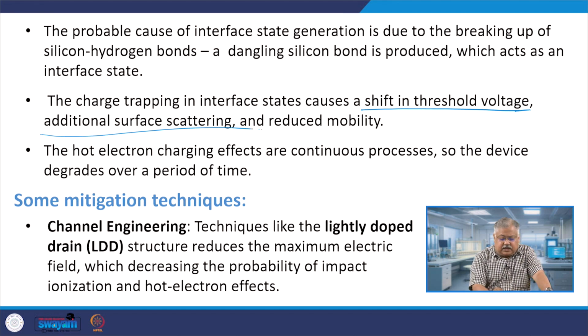Additionally, there will be surface scattering, and there will be a further reduction in the mobility. And the hot carrier charging effect is a continuous process. So, the device degrades over a period of time. Basically, the degradation goes on for a large amount of time.